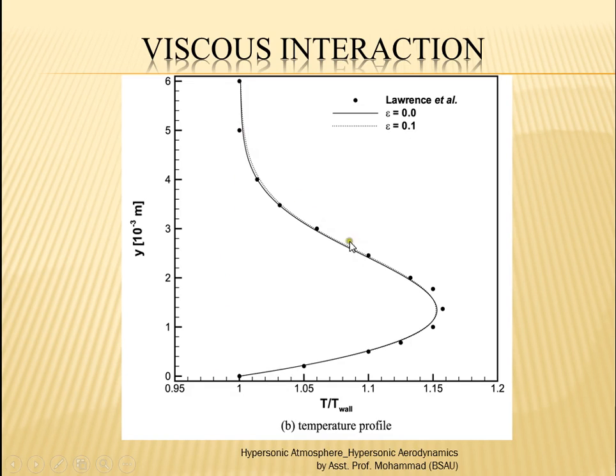But in between, because of the viscous dissipation, when a huge amount of kinetic energy is dissipated into heat, the temperature varies. The temperature goes very, very high just near the solid surface inside the boundary layer. It's not beyond the boundary, it's inside the boundary layer. This becomes very high.